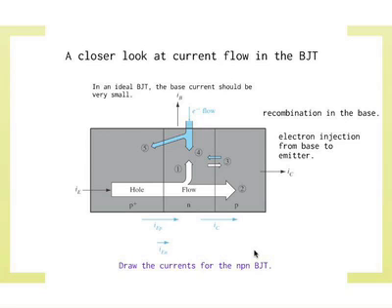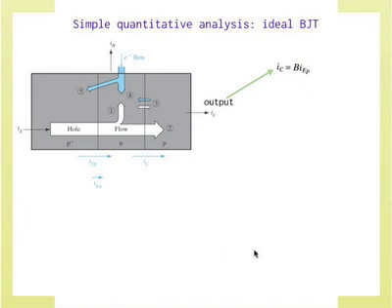It's an important condition. It's easier to understand this picture, but the actual operation is different. So this is what I was talking about. Let's very quickly see what this means. The collector current is some proportion, some B times the hole component of the emitter current, i.e. IEp. And that B essentially represents the probability that the hole that comes across from this junction makes it across to this junction.